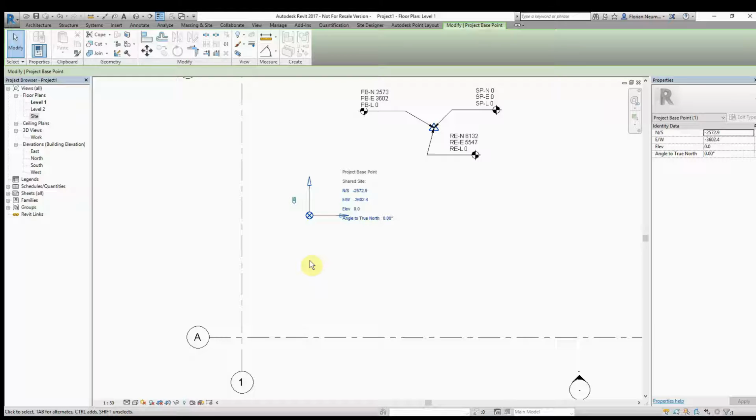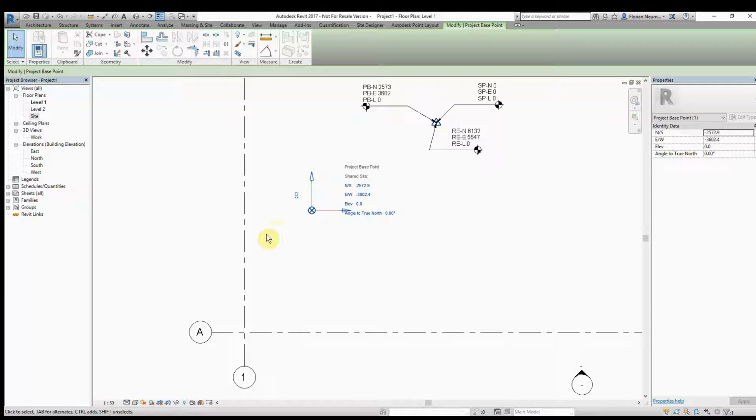What is a bad point? The geometric center of your building. Why? You can theoretically import it into a geometric center, and any DWG import might line up. But all of a sudden, during the design phase, the architect decides to change the size of the balcony, and then the geometric center is totally messed up. Okay, grid line A1 and nothing else. Believe me, it will always work.